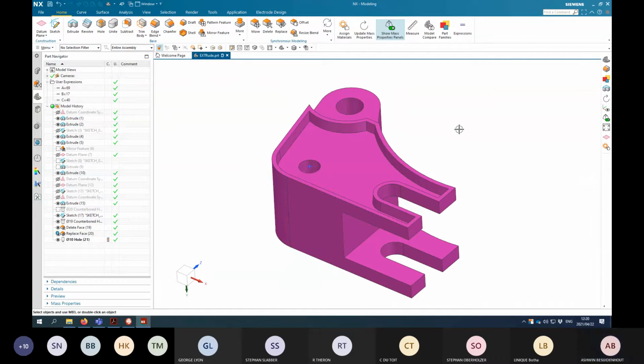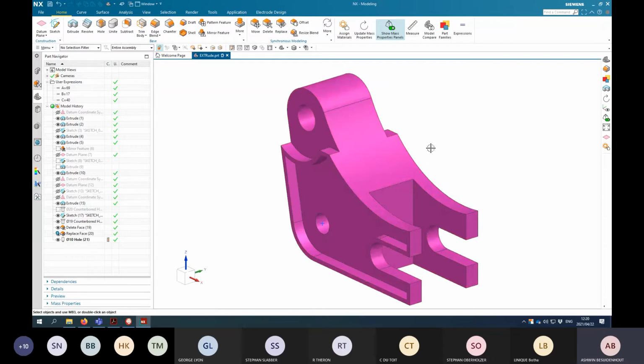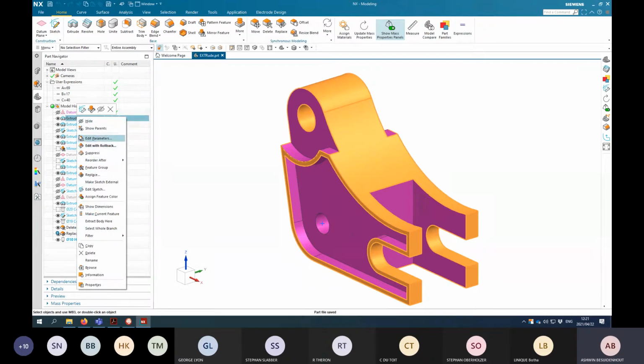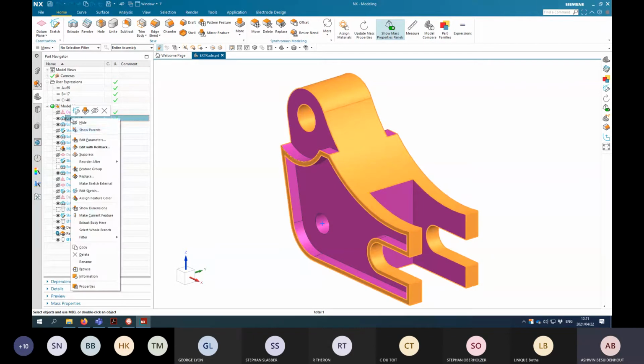I'm going to try and break this sketch, and hopefully it doesn't break. I'm not sure what's going to happen, but there are certain things that you should know. The sketches are built on top of each other, and it's called a parent-child relationship. Whenever you do something that's higher up in the tree, it will affect something that's lower in the tree because you have dependency. So the logical argument is the following.